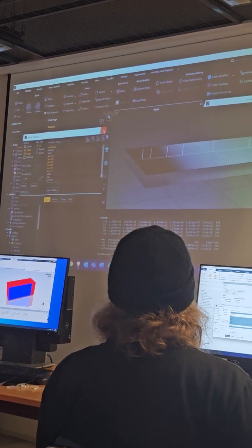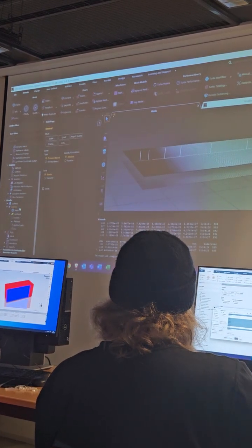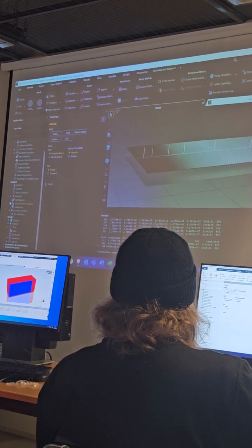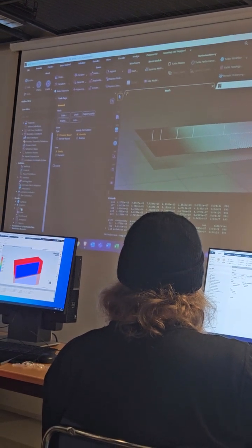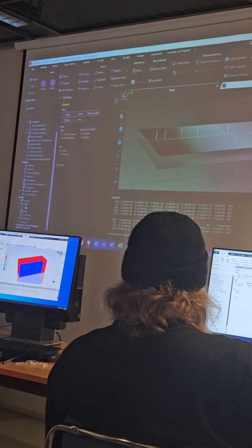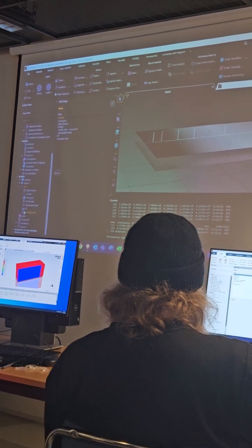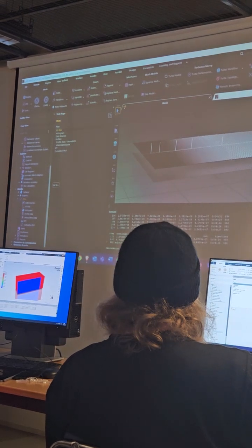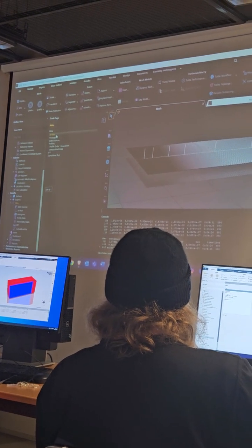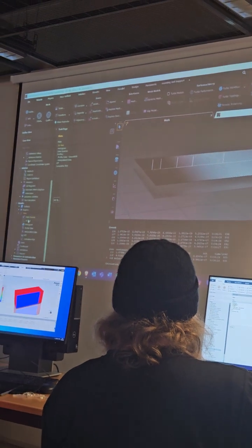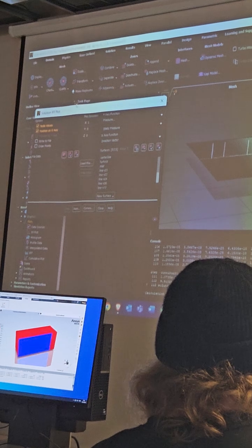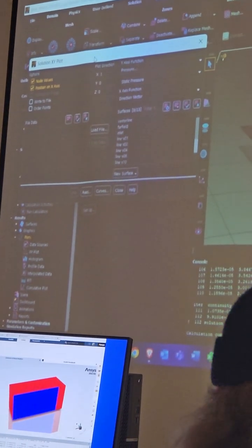So we can close this display, and now we can go in Results. There is this Plots. I double click on Plots, and here you can select this XY Plot. So you double click either on here or on the left here on XY Plot. So with this window you can plot your variables or you can save them.